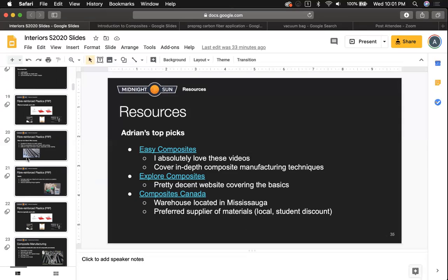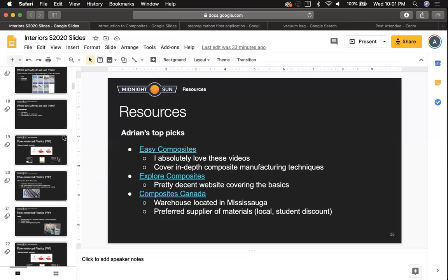One of the big downfalls I didn't cover on here, or pitfalls of carbon fiber, although it's very stiff and very light, is that it's electrically conductive. So I know that we were talking about using fiberglass instead, because fiberglass is more of an electrical insulator than a conductor.